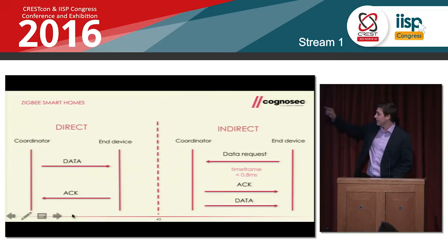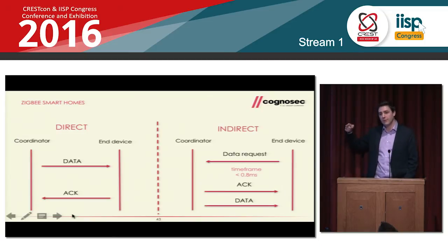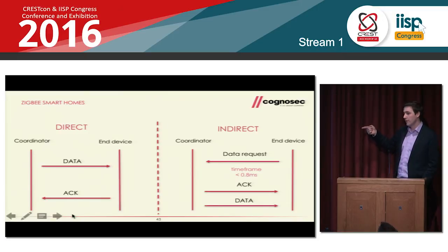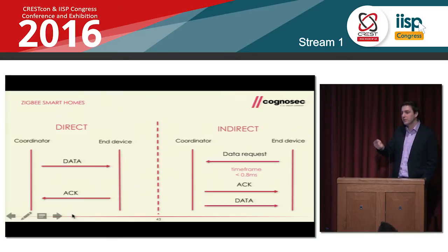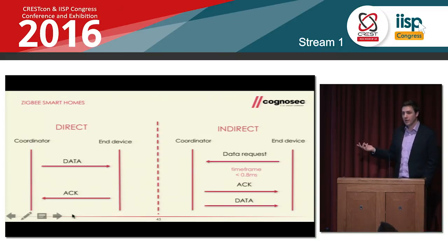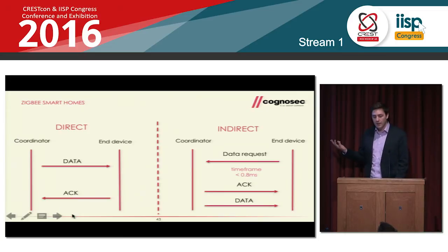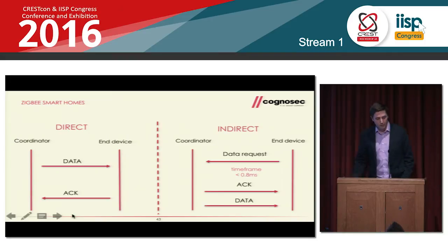And you have to be faster than 0.8 milliseconds to send an acknowledge with the flag set. In our scenario, I'm not the best programmer, so it takes a lot of time to decrypt the communication, get the counter sequences out there, build your new packet and send it. So using the software-defined radio, we were just 10 times too slow. So a colleague of mine then built his custom firmware for the Raspberry Pi, and now we are able to be faster than the hub and inject it before the hub replies.